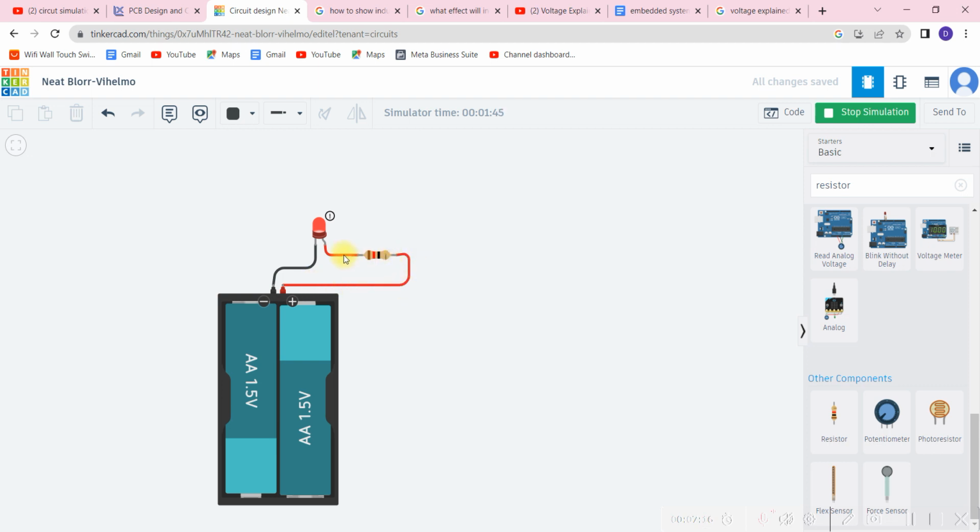Now what you do is you can steal some of that energy from the battery. As current is flowing through this wire, you can steal energy by inserting components into the wire and causing the current to flow through them. You're saying, I've created a path for you, but before you can get to the negative end of your battery, you must pass through my components, and in doing so, you must release some energy for me to use. So that's what happens here. This voltage will force the current to flow through this place, and by the time it hits this resistor, it will drop some. This resistor will take some, and then this LED will take some, and then the remaining will go back to the negative end of the battery.